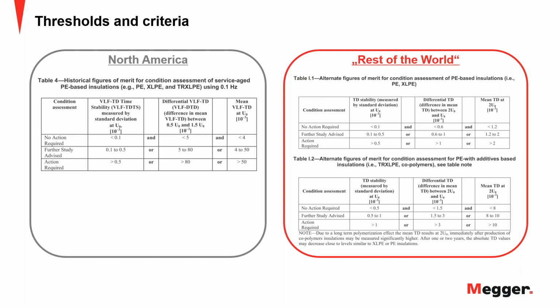This is, you know, they have tables for, you know, quote unquote rest of the world, which, if you take a look at them, you will see differences. But in the IEC world, there's no tan delta guide comparable to the IEEE guide in terms of evaluation criteria and whatnot. And remember, the test practice is also different. They go up to 2 times operating voltage even.